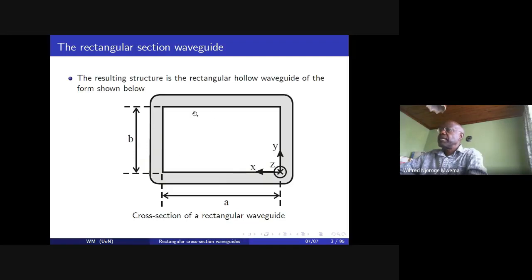So this is what has been done. Now imagine this was a parallel plate with a top and a bottom plate of infinite extent. Because we have seen that the fields are sinusoidal in that direction and sinusoidal in the direction of propagation, we can choose where the E becomes completely 0, because the sine will always be crossing the 0 line, and therefore place a perfectly conducting plate, and we'll get one like that.